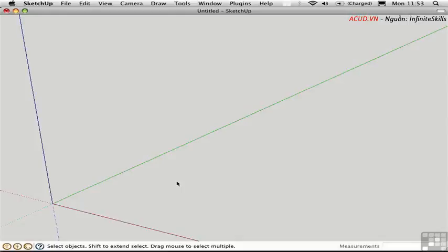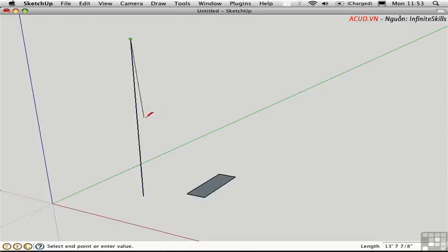This video is about SketchUp's built-in divide tool and the divide with construction points script. Let's say we're building a stair. I'll start by drawing a rectangle representing an individual step in plan. I'll make that 11 inches deep, 3 feet wide. Then I'll draw a line off to the side someplace in the blue direction that measures the height of the stair. Let's call that 9 feet for this demonstration.